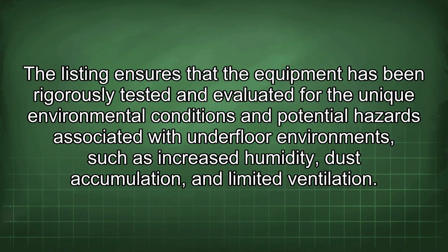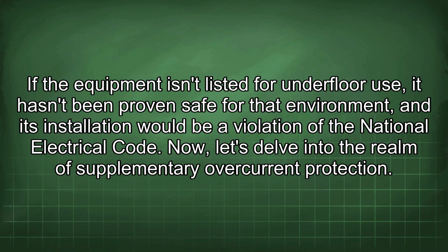The listing ensures that the equipment has been rigorously tested and evaluated for the unique environmental conditions and potential hazards associated with underfloor environments, such as increased humidity, dust accumulation, and limited ventilation. If the equipment isn't listed for underfloor use, it hasn't been proven safe for the environment, and its installation would be a violation of the National Electrical Code.